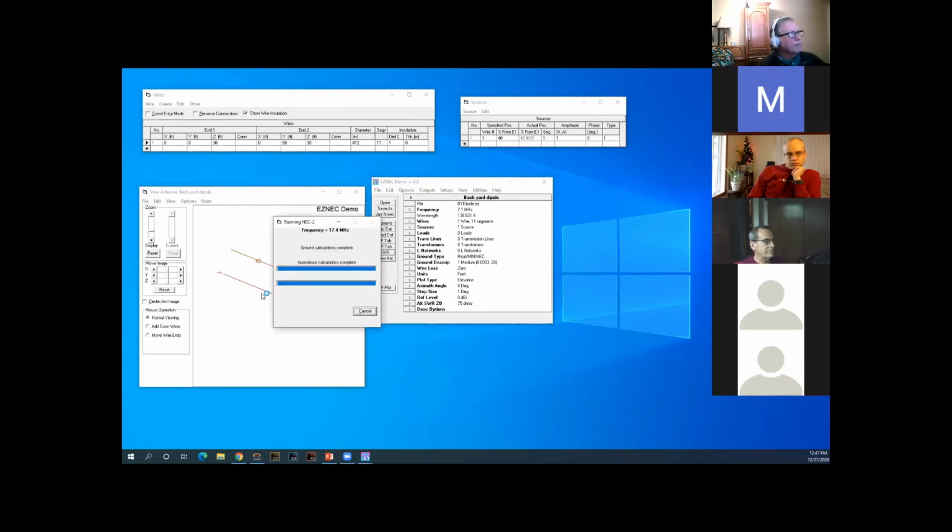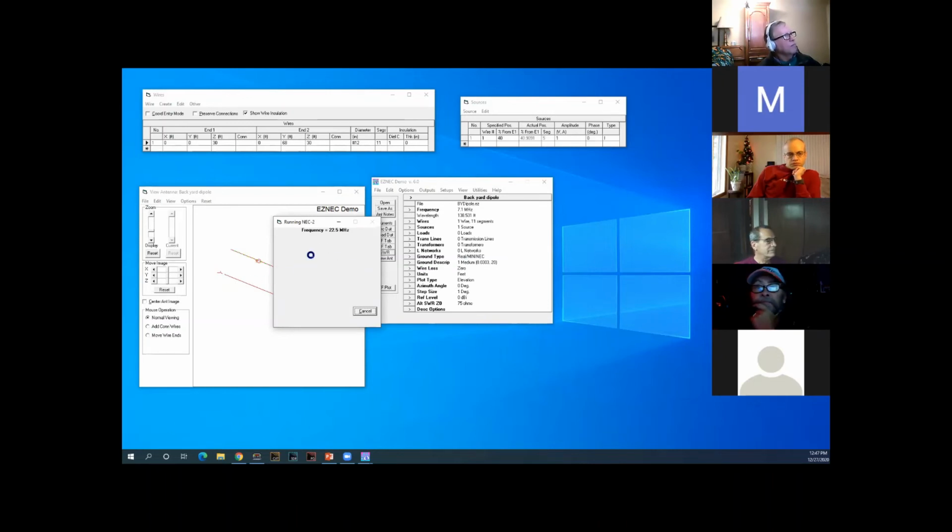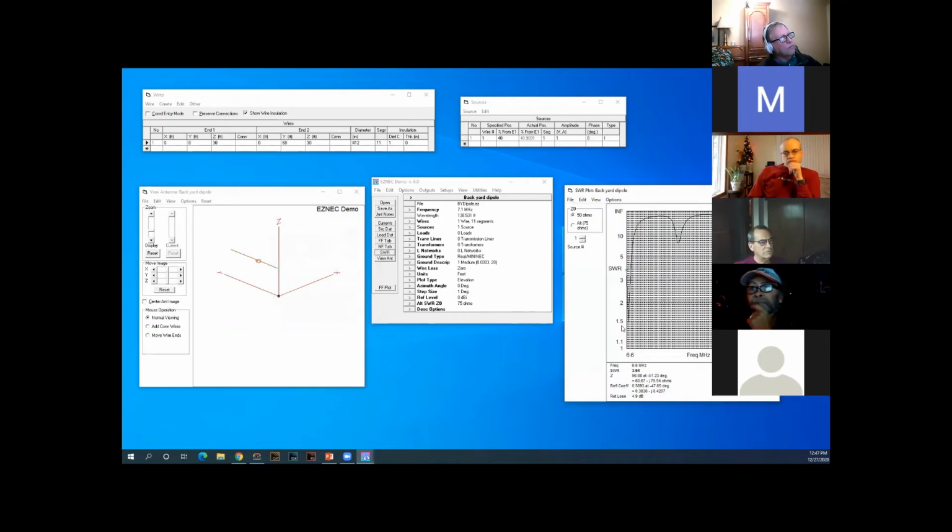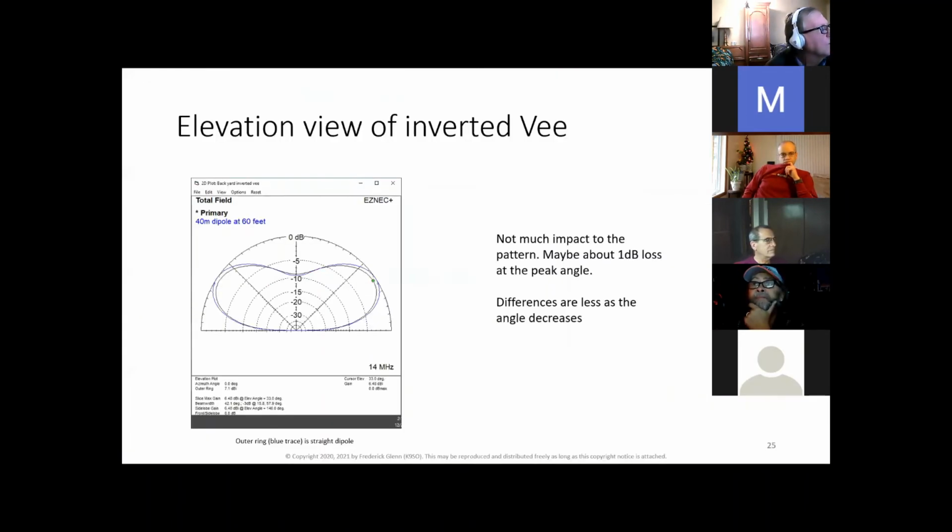And you see my computer is doing all kinds of things over here, calculating at every frequency. Now, here's what we have. It looks like we have a resonance around 6.8. We have another semi-resonance over here at 14, another resonant point here at 21. So you can see kind of off-center fed dipoles, you might actually get some resonant points. Lousy SWR, but they are resonant points, so they can actually work. Anyway, I am getting a little off subject here.